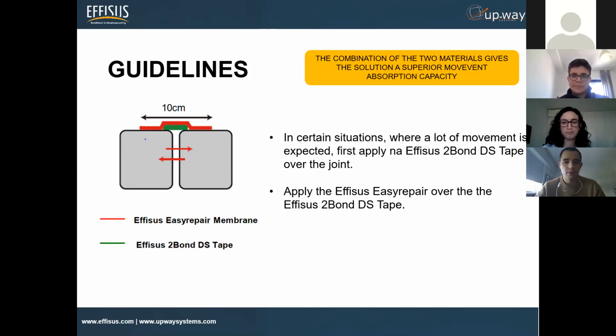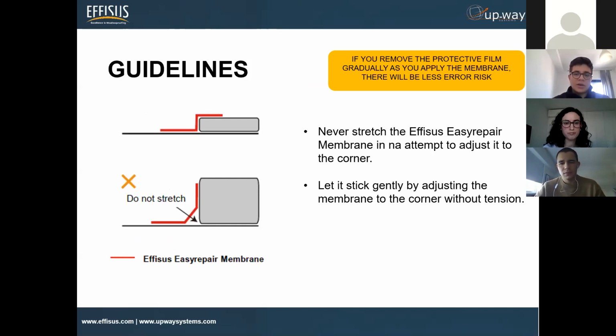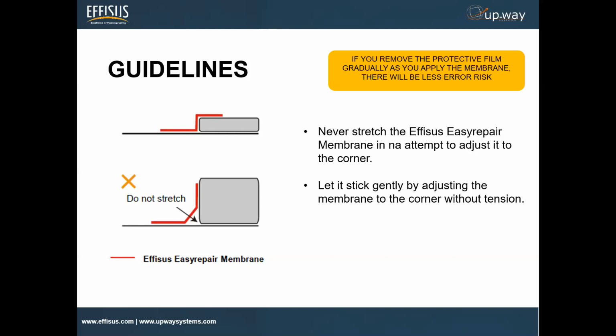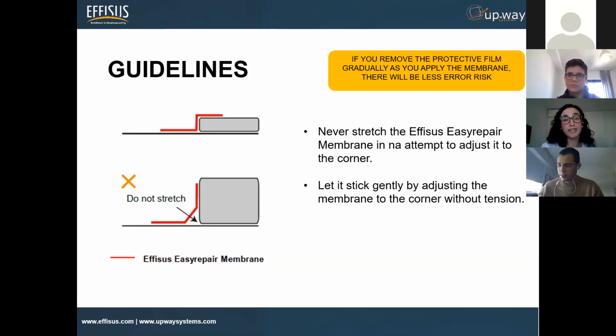Yes. And here, Mar, what we have here. Yeah. In this case, it's when we have a different height between the application. So we have to follow all the perimeter and apply this membrane without any air in the middle, especially in the corners. Normally when we have something in the air, we say, okay, press, and then it's done. No, we can't do that, because the membrane will break.